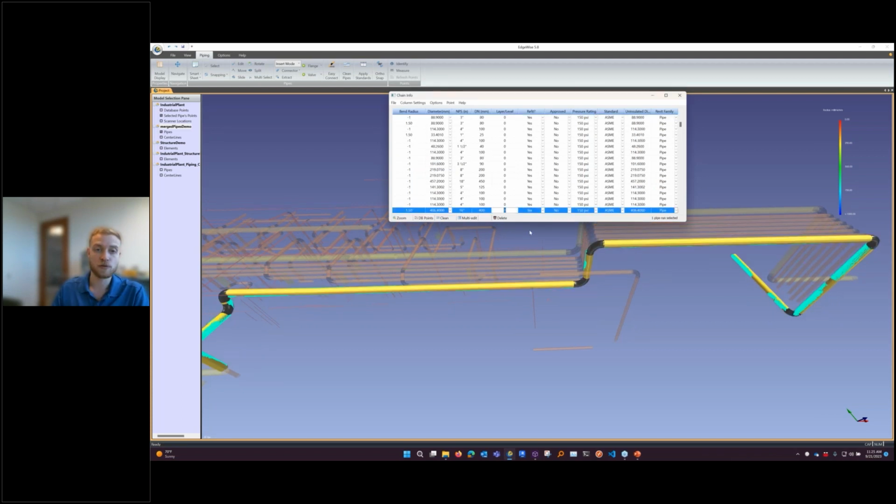information. This can be really useful for certain workflows, especially with what we're going to do when we import this into E3D. We can break the model up based on these and do different imports into E3D. It's in the naming convention for the equipment. So that's another way you can organize things. Just having this here can be really nice for simple organization for what we're going to push over when we go to E3D.